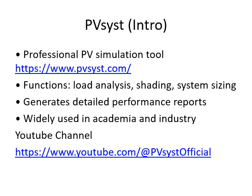One is PVsyst, the most widely used one, but you need to get the license. Its function is mostly load calculation, shading and system sizing, like how many PV panels you will need. It can give you a very good idea, then generate a detailed performance report, and it is widely used. Whenever it comes to which software I should use, the most common answer is PVsyst.